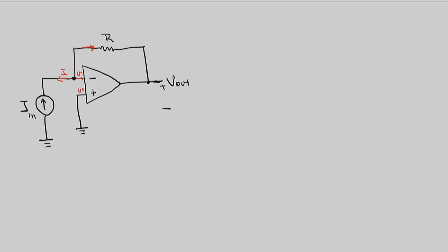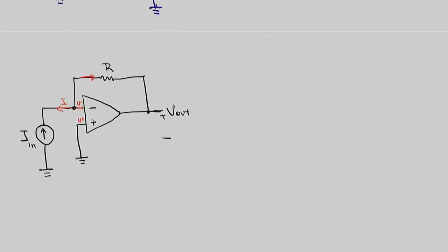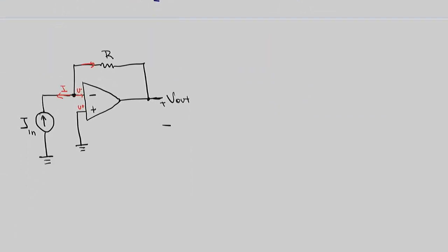Circuit analysis for this example, which we had there. Same thing. We checked that there was negative feedback. If it's negative feedback, I can write with all the confidence I have that U plus equals U minus. I can ask my students, what is U plus? 0.